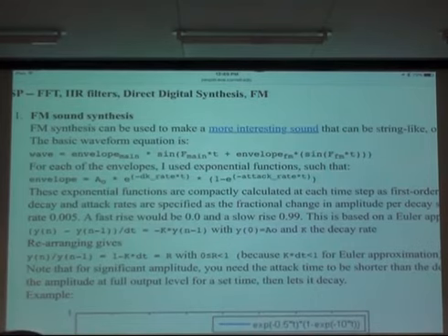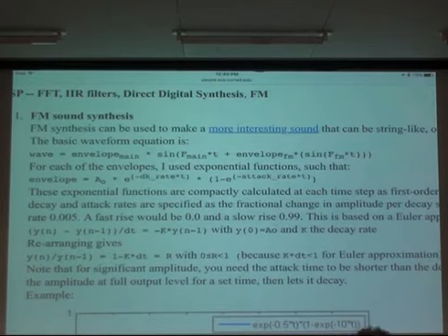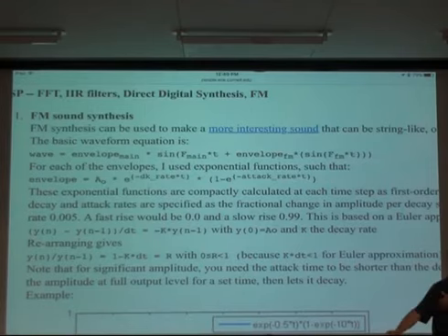Yes. So, how do you recommend we start the motor initially? How to just start the motor? Well, in main, you could set the pulse width modulator to 50%. In other words, when you initialize the OCX unit that you're using for the pulse width modulator, set the initial width to half of the period or 3/4 of the period. That'll guarantee that the motor turns on unconditionally.